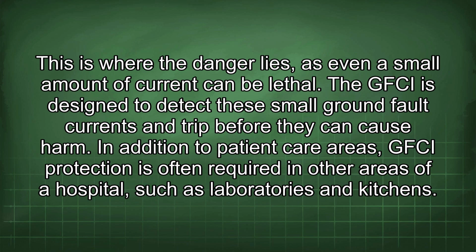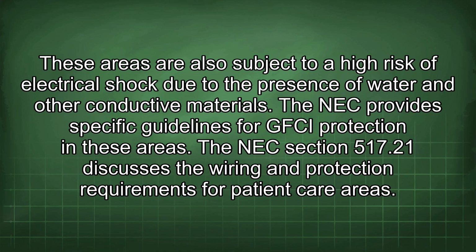In addition to patient care areas, GFCI protection is often required in other areas of a hospital, such as laboratories and kitchens. These areas are also subject to a high risk of electrical shock due to the presence of water and other conductive materials. The NEC provides specific guidelines for GFCI protection in these areas.